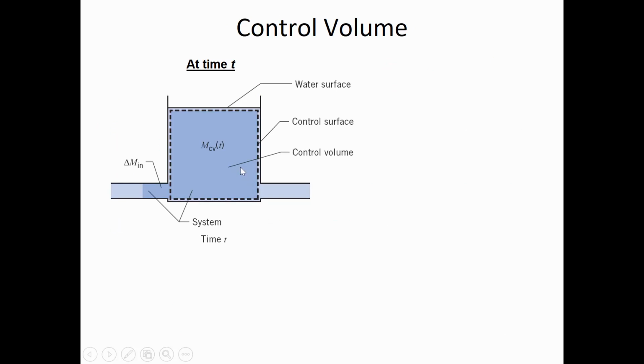Okay, so here's an application of the control volume approach, and it's best illustrated with a tank. The reason why that's important is because it's a pretty typical storage location for fluids. And right now, at time t, what we can see is there's a certain amount of liquid inside the tank, and liquid is coming into the tank and it's exiting the tank. But the darker blue liquid is our system of interest. So it's a fixed number of particles, and there may be other liquid particles besides our system that exist, but we're not necessarily going to be keeping track of those other particles.